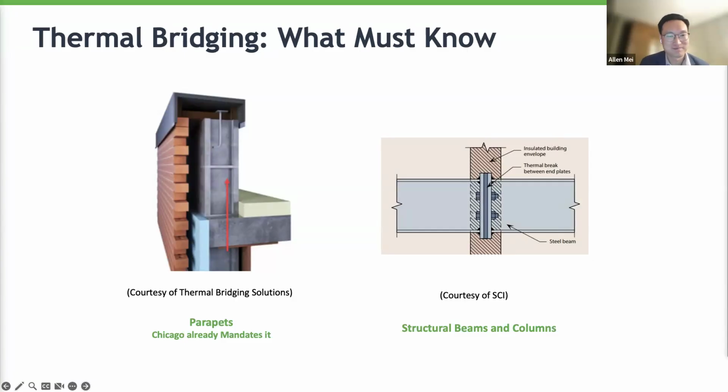Yeah, and just real quick to speak on the structural beams, we've been part of projects where we've seen significant connectivity through those structural beams into the space and plenum spaces, so much so that we've seen sprinkler heads popping and various temperatures within plenum spaces where those beams are coming through from the outside. So it's significant how much cold air possibly comes in from that thermal bridging, or how much space temperature varies due to that thermal bridging.